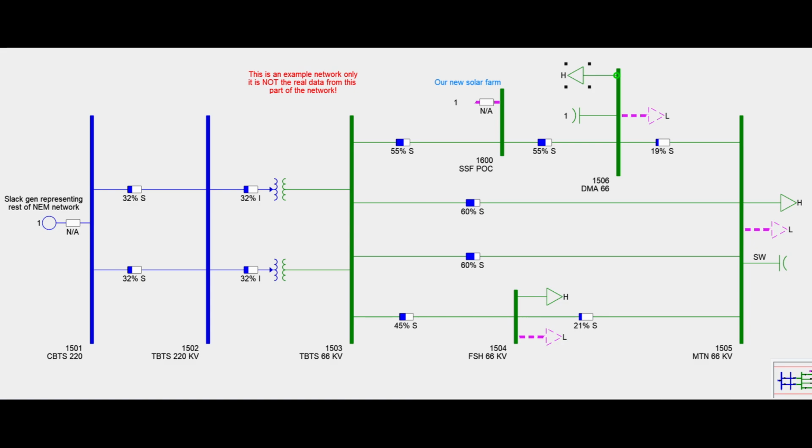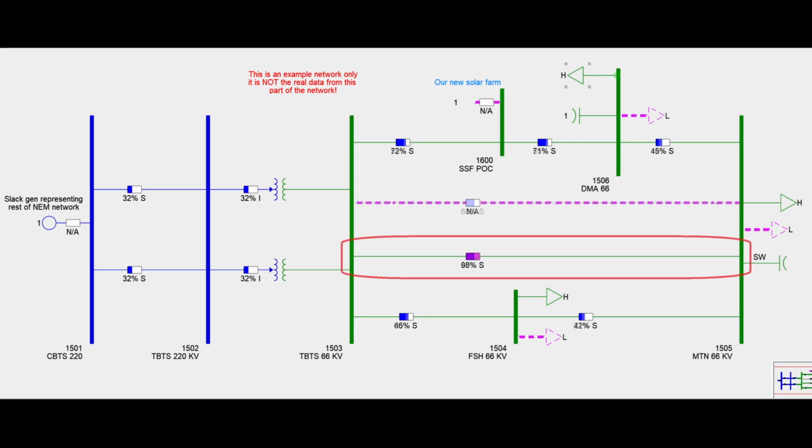If we simulate a contingency, known as a system N-1 condition or one line out of service, if we disconnect the most heavily loaded line, which is one of the Tyabb to Mornington lines, we can see the remaining second line hits 98% of its thermal capacity.